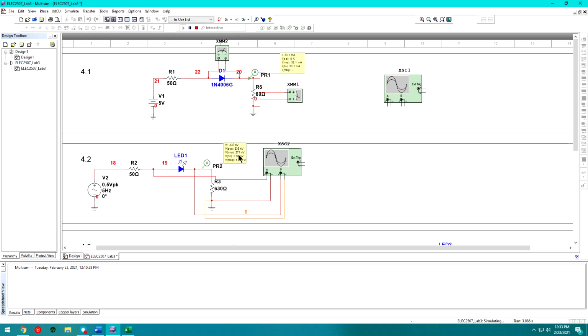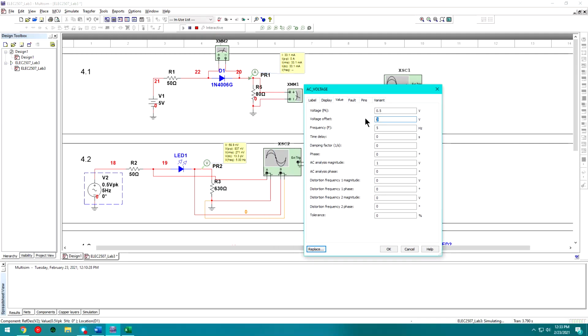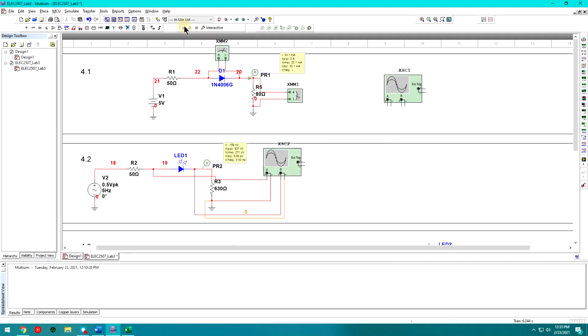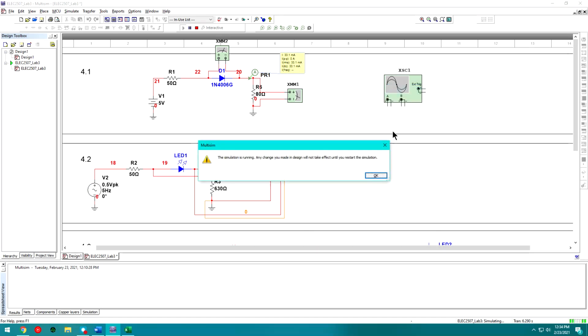And we can see that right now we have 0 volts DC, right? Because I haven't increased the offset at all. So my offset that I'm looking for at this particular node is 3.15 volts. So chances are I'm going to have to be higher than that on my offset to actually achieve that, right? So let's try 4, just for a starting point. And we can either go up or down depending on what we see. Yeah, so we see we're only at 2.1 volts DC on that node. So let's increase that a little more. 5 volts maybe, 5.5 maybe even.